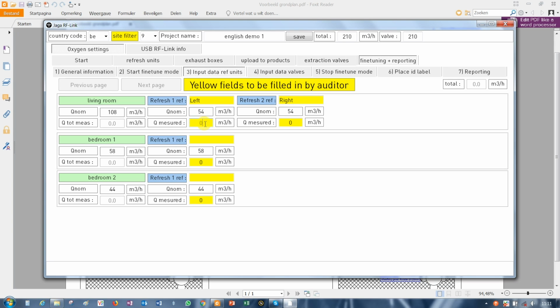This voltage can be adjusted using the buttons within the control panel to measure the actual values you're getting, or give you the actual values you need based on ductwork lengths, etc. So in this case we have measured this one running at 53, and this one we have retuned and is actually running slightly higher at 55.